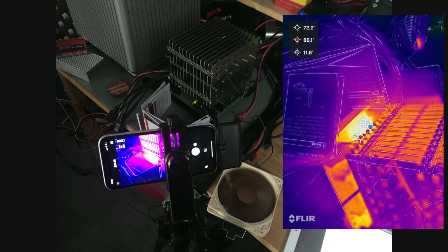So therefore we'll take the absolute temperature values that are observed with the FLIR camera with a grain of salt. Still, it is relevant to look at difference of temperatures observed with the FLIR camera. We'll do this towards the end of this analysis. And in addition, we are looking over IPMI to use that sensor to also observe the die temperature of the X570 chipset. Like this, we have 2 independent measurements, and if with both measurements we are coming to the same result, we have established credibility that the results are actually valid.